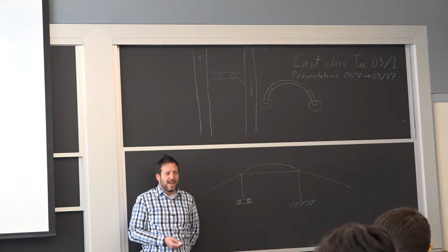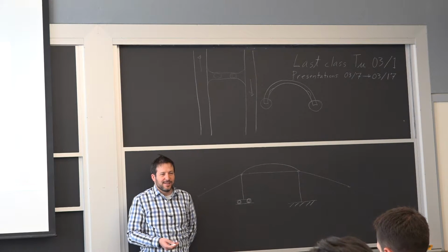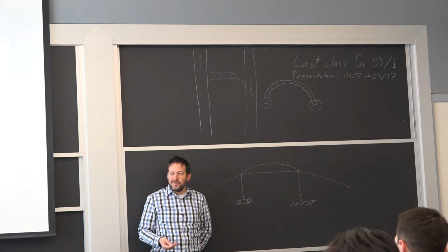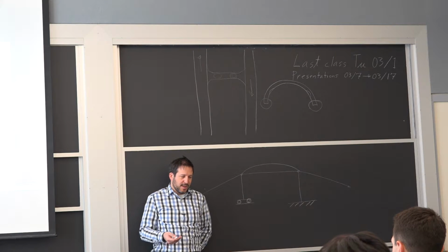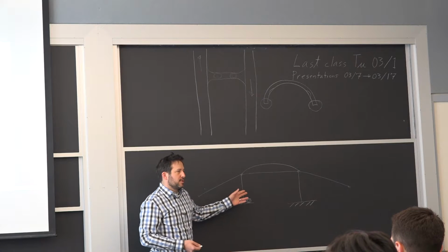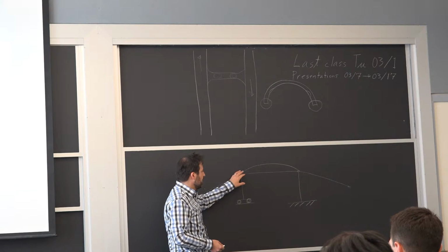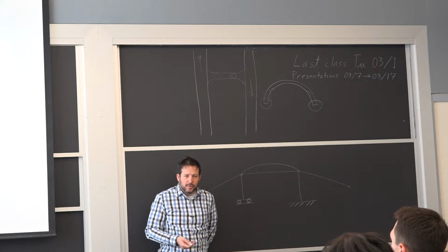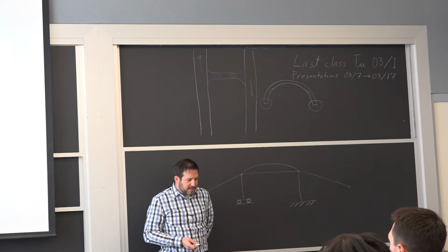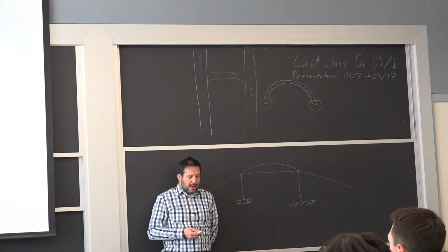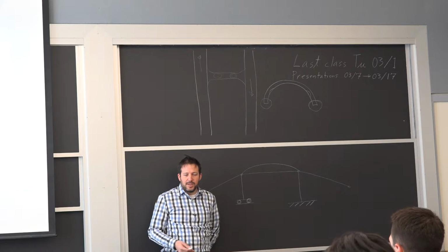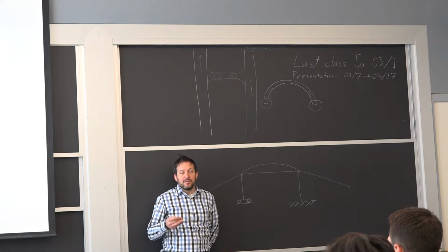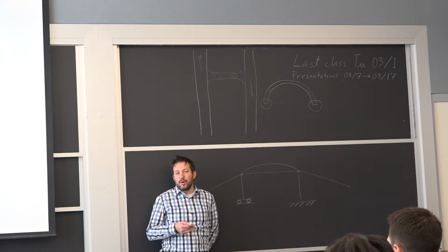Well, they're looking for things that have been a problem in the past, not necessarily everything that could potentially go wrong. And that's where things just become very, very difficult, even with experience. And now what they do with these old bridges, there were other issues, of course. There were some issues about the thickness of some of the materials to make the joints. There was some corrosion of those members as well. But that's really where I say that as opposed to building something and doing a proof load test or a test run, when time gets involved, your risk of failure always goes up.